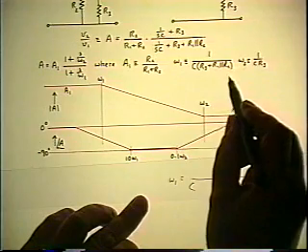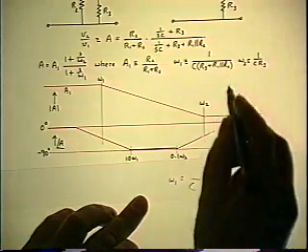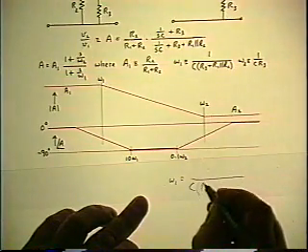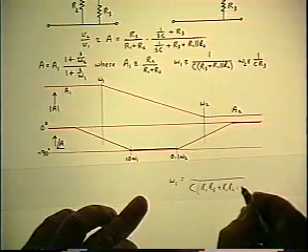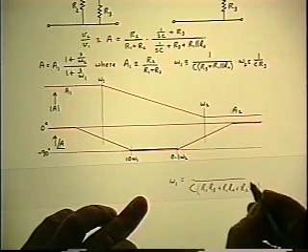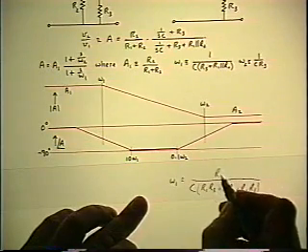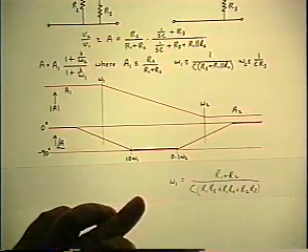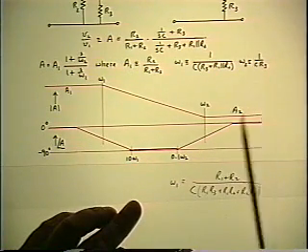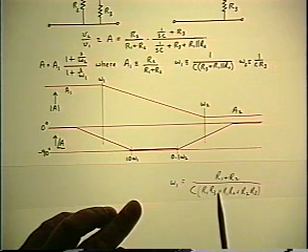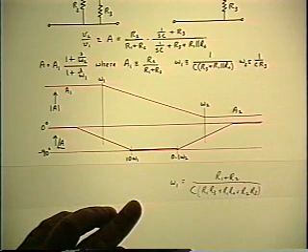Parallel combination of R1 and R2 would be product over sum, and then you cross multiply, and you'd get R1 R3 plus R1 R2 plus R2 R3, and in the numerator we would have R1 plus R2. So if you look at that and compare it with the omega 2, it is no longer obvious which one is lower.